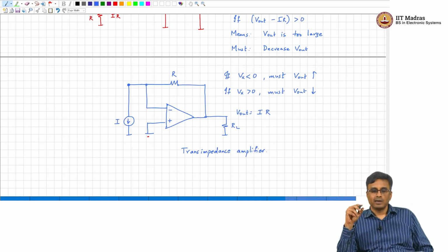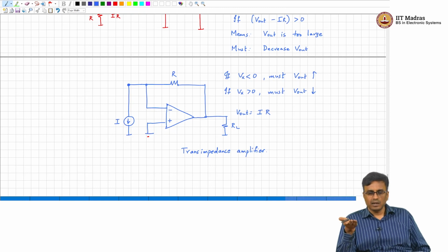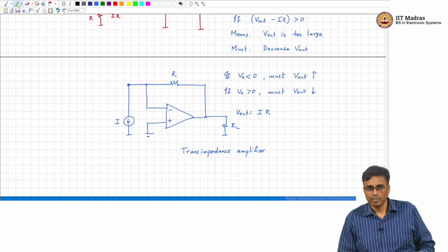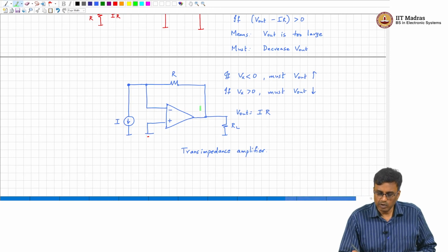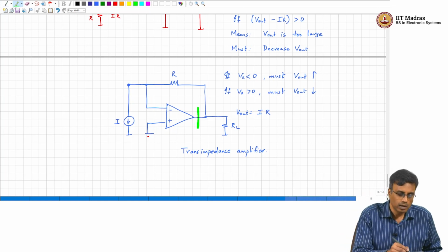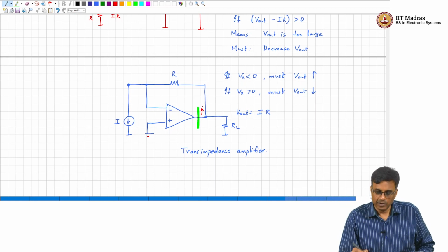I mean, we derived the circuit from scratch, correct. But if you are looking at this circuit for the first time, the first thing to do is make sure that there is negative feedback. You break the loop, you yank this guy up. What happens to this voltage?